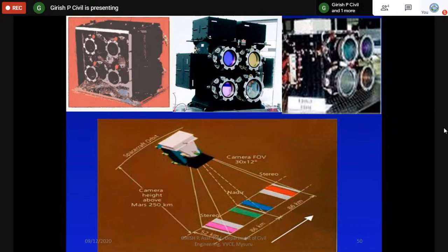It is capable of capturing various bandwidths of the electromagnetic spectrum, and at a time it is possible to cover 80 to 90 kilometers in length and a width of 52 kilometers. The area can be extended many times, but the resolution will vary. If we want to collect higher resolution, the area will be compressed. If we get a larger area, the resolution will be lower.